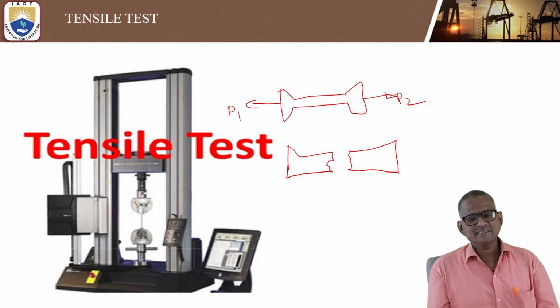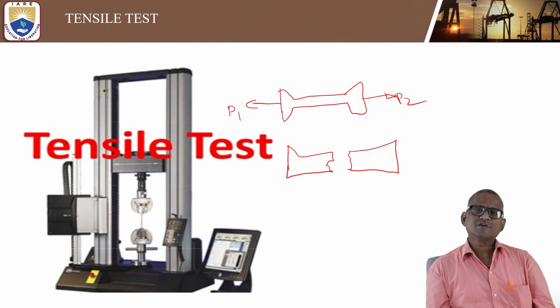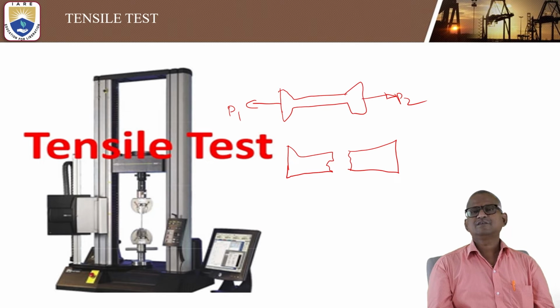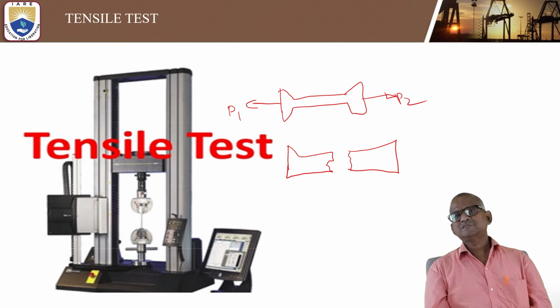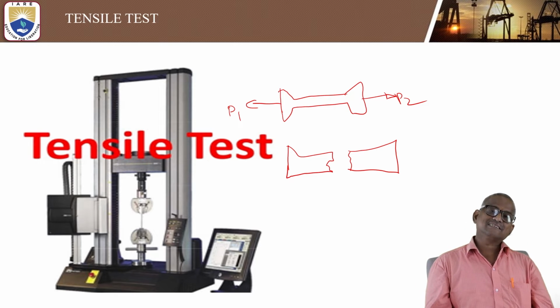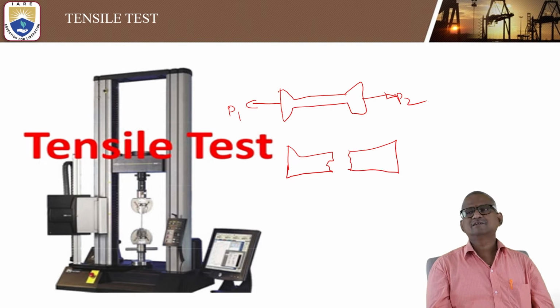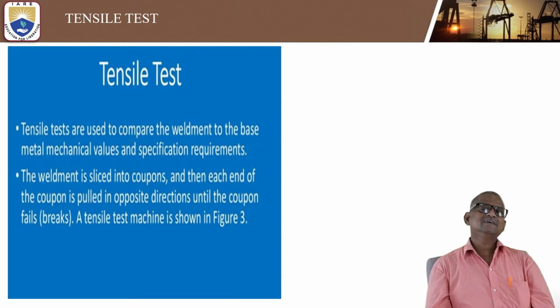Even in such cases, the tensile test is one of the important tests after performing the welding, or during the welding also. You have to test how much tensile strength can be obtained in this component, how much compressive strength may be obtained, and what the impact strength is. For impact strength, a notch specimen can be prepared and tested in this case. All destructive tests will be discussed one by one. Okay, now let us see what is meant by a tensile test.